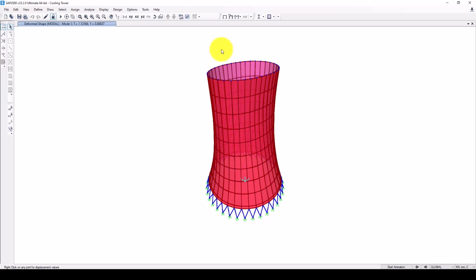So this is almost acceptable in case you want to use that equation, 0.1 times n, where n is the number of stories. So this is okay because it's almost one story here, one story here and one story here, total stories.